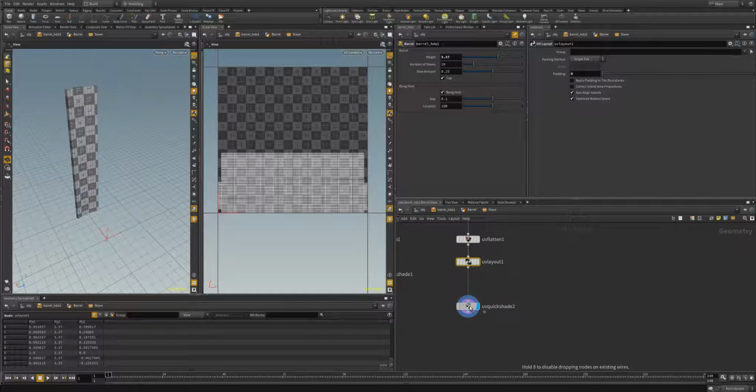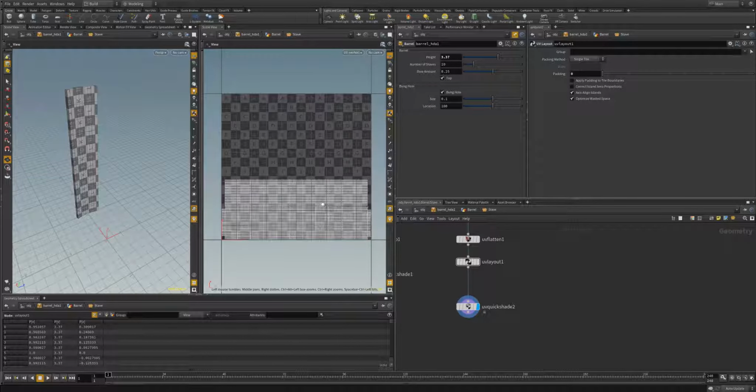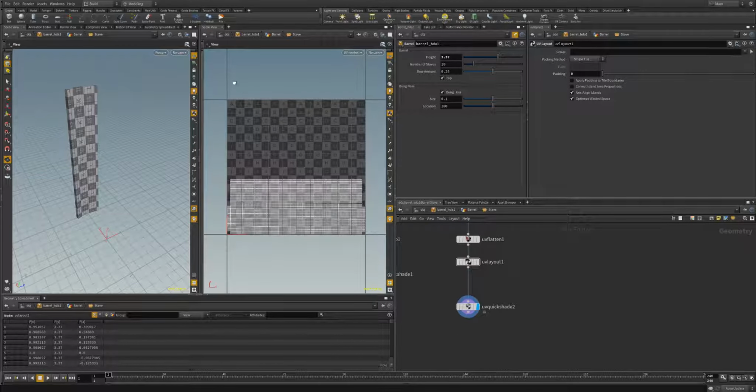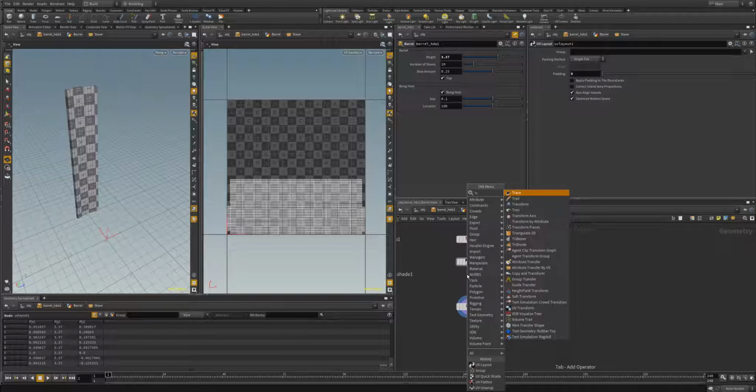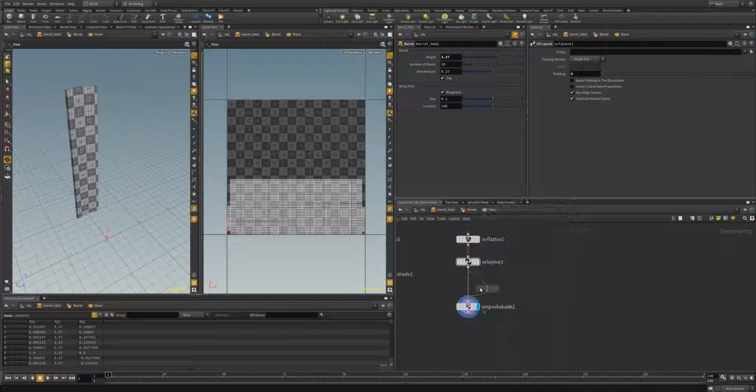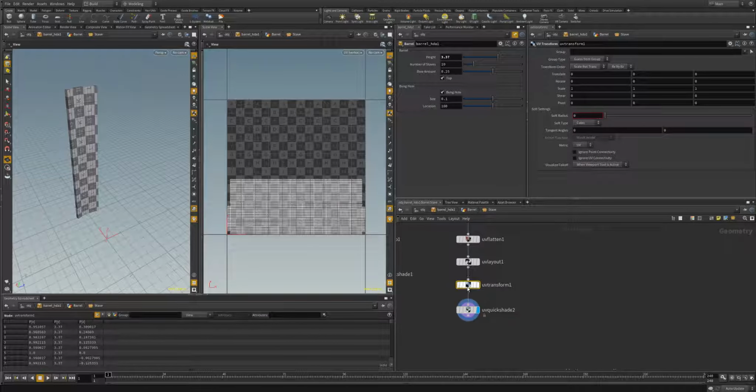And after we get that layout, we're going to need a transform so that for my material, I like the wood grain going vertically, so up and down. So I'm going to want to rotate my staves to go up and down as well. So we'll do a UV transform here, and we're going to rotate this by -90.